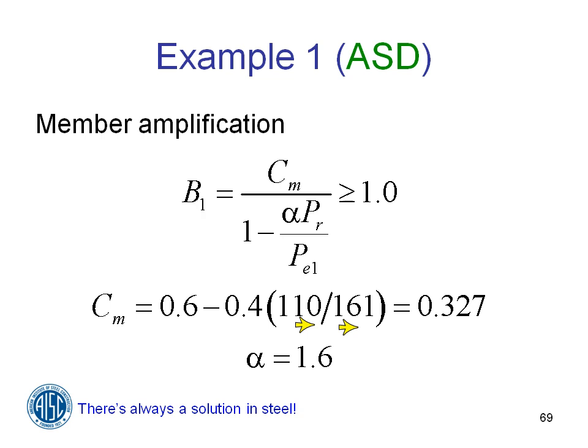Okay. And then one of our attendees has asked if you have any thoughts on applying the direct analysis method in a bridge design situation concerning either a top chord of a truss or, say, a rib of an arch? Well, I'm not a bridge guy, and certainly the AISC specification doesn't apply to bridges. But I know that there are engineers who have used this kind of an approach for structures other than buildings. And it comes from a well-understood understanding of the behavior of structures.